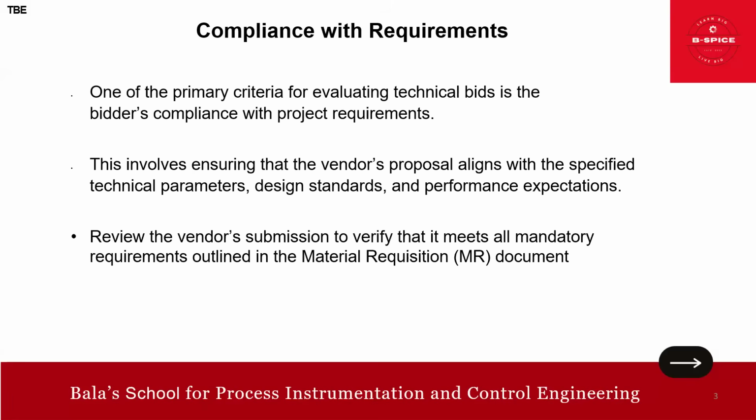Review the vendor submission to verify that it meets all the mandatory requirements outlined in the material requisition document. That is why the MR is important. The specification is very vital, and equally this MR, because there are so many requirements and prerequisites, and not only commercial ones. All this they need to meet. So this is about the compliance with project requirements.